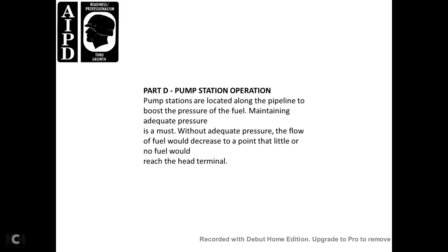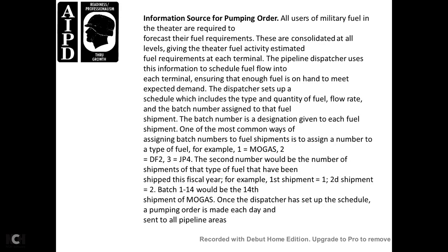Part D, pump station operation. Pump stations are located along the pipeline to boost the pressure of the fuel, maintaining adequate pressure. Without adequate pressure, the flow of the fuel would decrease to the point where little or no fuel would reach the head of the terminal.